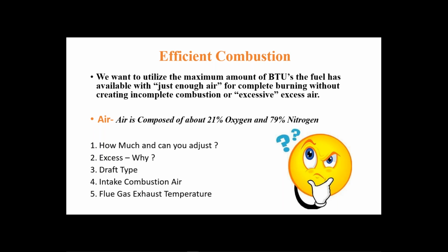Excess, why? There is always excess air. Why do we need excess? We're going to talk about that in pretty good detail. Draft type, positive draft, negative draft. We have both in our industry today. Intake combustion air, especially on more modern high efficiency equipment. We're doing direct vent and direct intake today. So intake combustion air is extremely important.